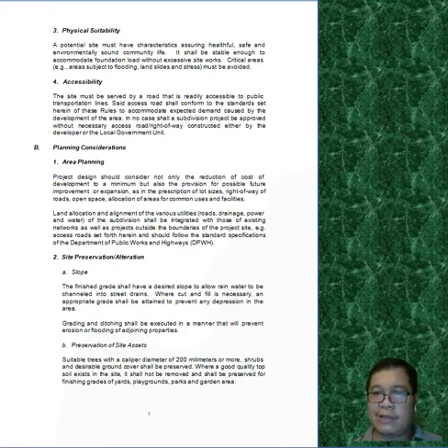Because even if you locate them in a place that is far away, these people can afford the transportation systems. They can buy their own car. So when you design for socialized housing, you must make sure that the place where it's located has a public transport system available as much as possible. Or when you do that subdivision, the developer must work in parallel with the local government units to ensure that there's going to be public transportation or jeepneys passing by that area.